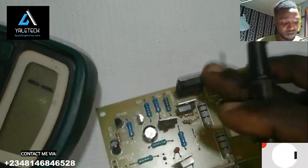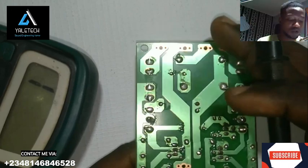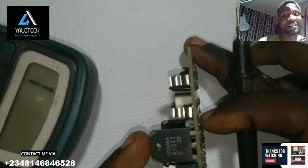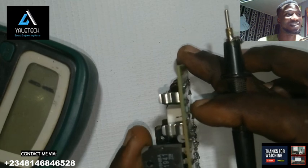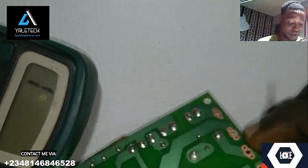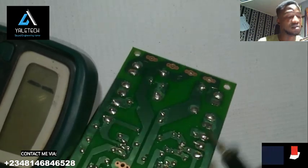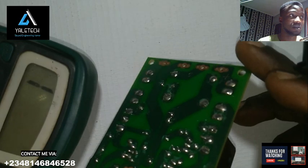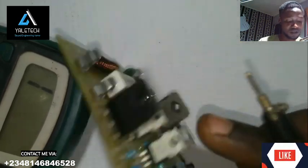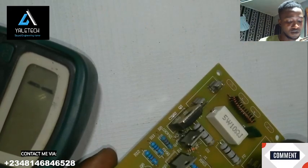For this one it is giving me a normal reading, but to be on the safer side, because sometimes you may see physical damage on a transistor and it may claim to be 100% intact whereas it's bad, to save yourself that stress, just desolder one or two legs, then read it properly. So that you save yourself that doubt. That's just one of the ways to go about it. So I believe you know how to test your transistor very well. And this is B423 and the rest.